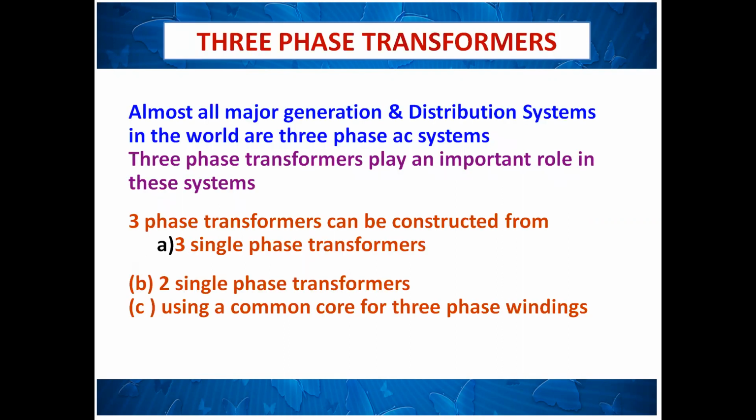So this is the construction. Why do we require a 3-phase transformer? Because our major generation and distribution are in 3-phase. That's why we require a 3-phase transformer. Construction is like a bank of 3 single-phase transformers, or using a common core with 3-phase winding.